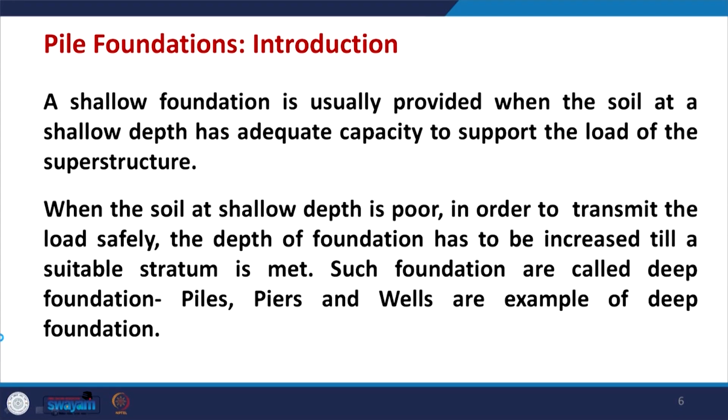Civil engineers typically know what the use of piles is. You know that shallow foundation is usually provided when the soil at a shallow depth has adequate capacity to support the load of a superstructure. If the soil has adequate capacity and loads are not very heavy, then we can go with shallow foundations.